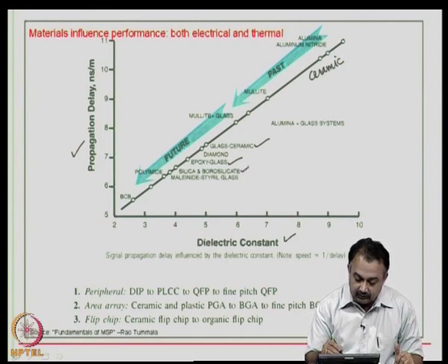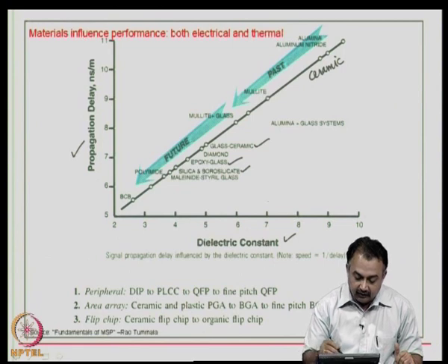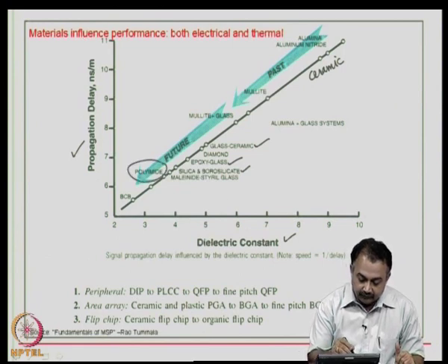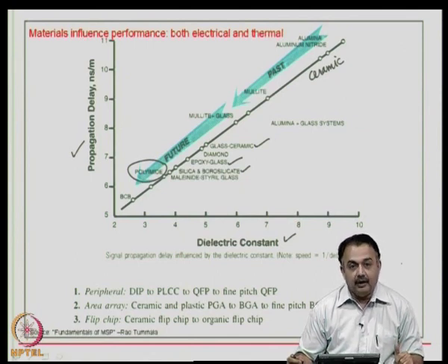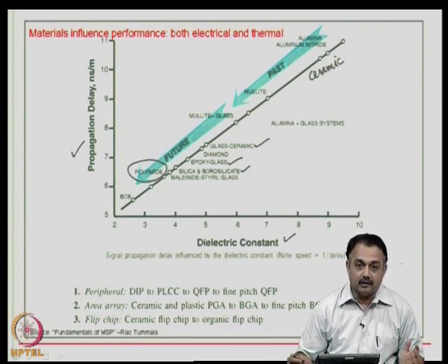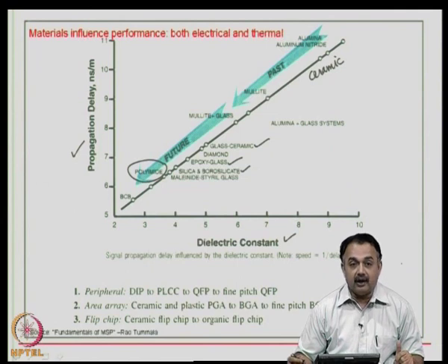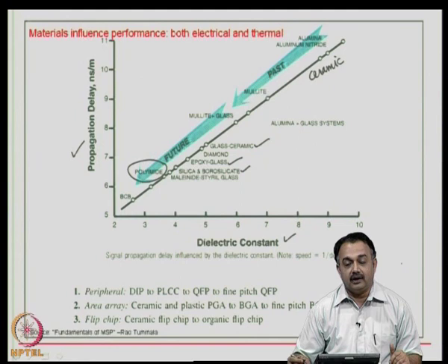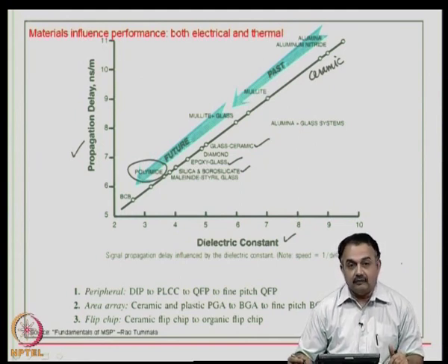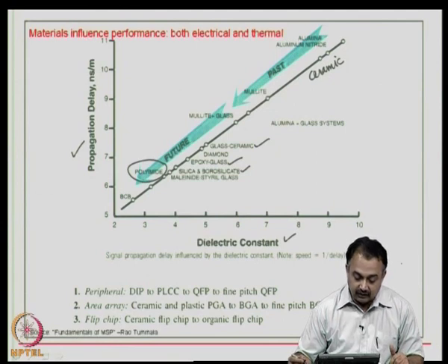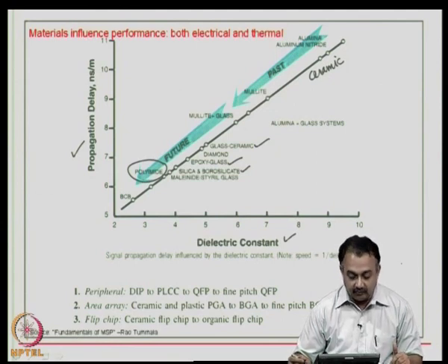Silica is being used, borosilicate, and then polyimides have been used for high performance applications. In terms of dielectric constant, it may be superior, but if you look at other properties, for example, moisture absorption, it could have higher moisture absorption, and therefore, it could decrease the electrical performance, but at the same time it is a current material, and it could be a future material.